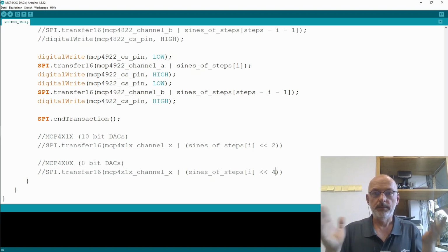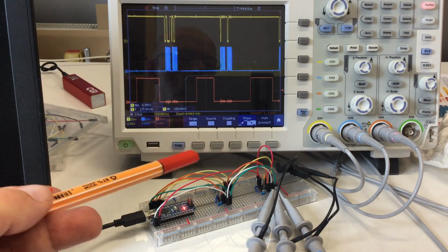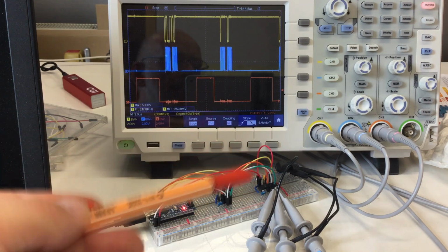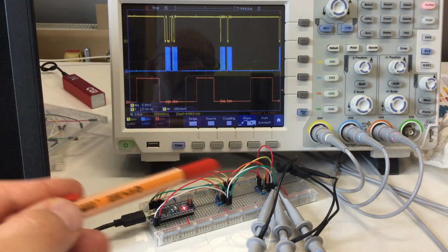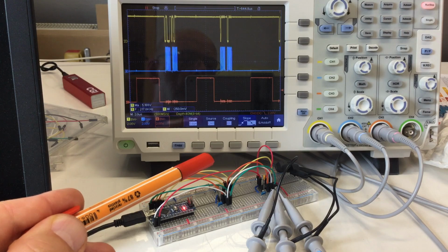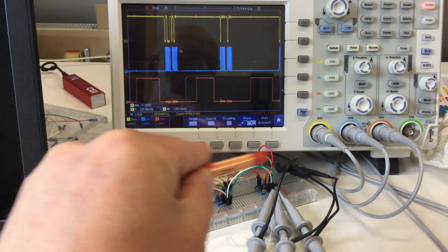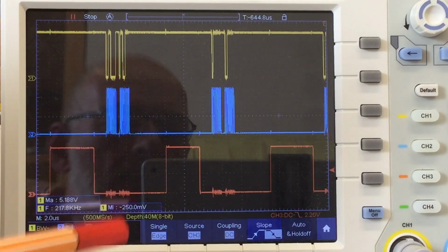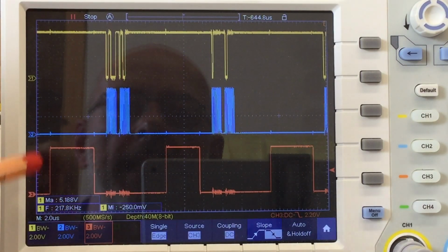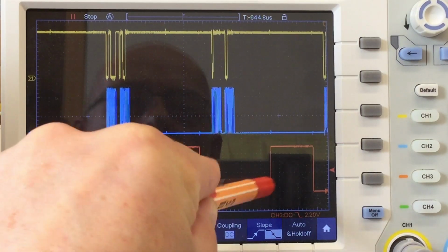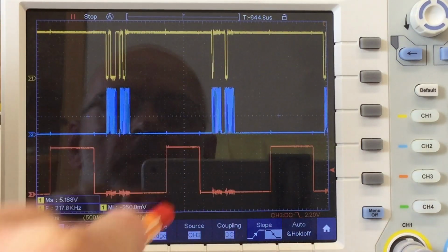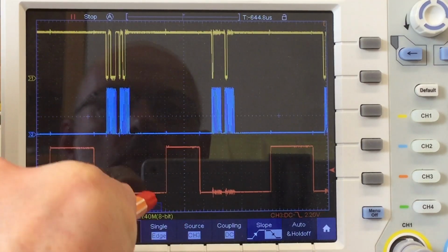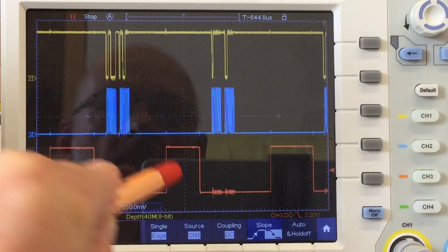That's all the code. So, why is my code generating an 84 Hz sine wave so much faster than using the library, which just managed to generate a 70 Hz sine wave? To answer that question, I went back to probing the SPI bus. Looking at the big picture, you see that I can now fit 3 chip select highs on the oscilloscope screen, and I'm using the same timescale as before, 2 microseconds.